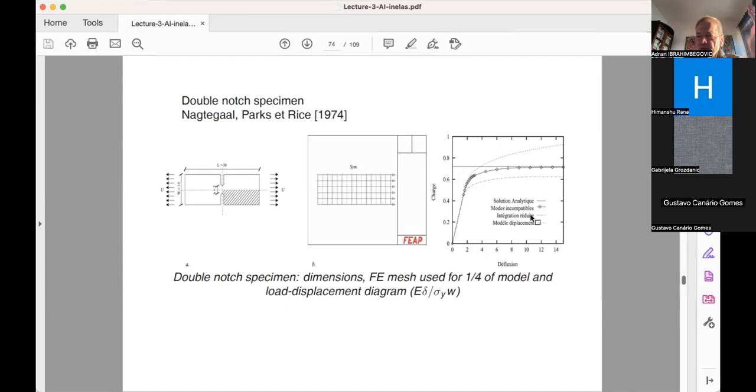There are some remedies to this. If you take reduced integration, that would mean that you take a single point for the, let's say, volumetric part and 2 by 2 for the deviatoric part. You get somewhat better results, but still not good enough, because the 4-node element still remains rather poor with bilinear interpolations. But if you add incompatible modes that we discussed already in the 2D case, basically you start getting a nearly perfect result, because you get rid of the locking phenomenon.